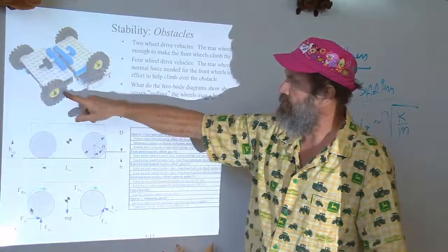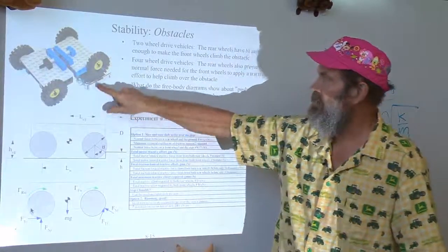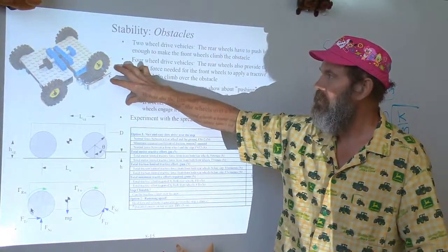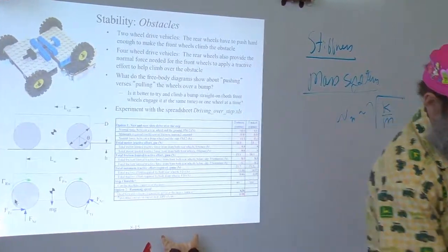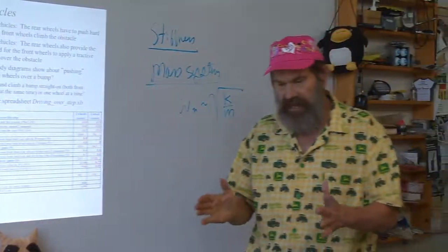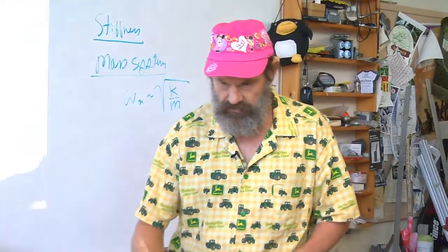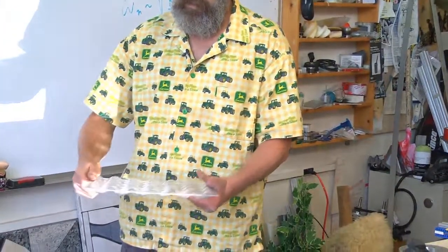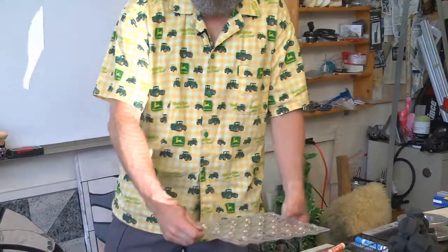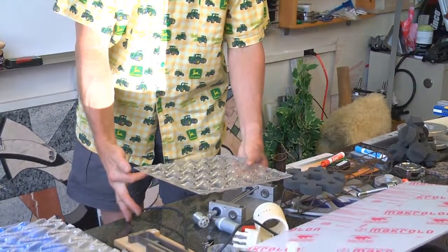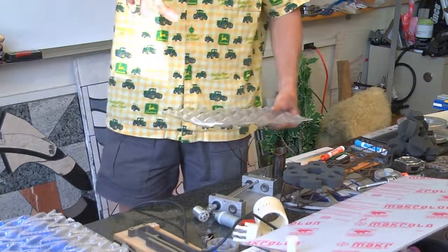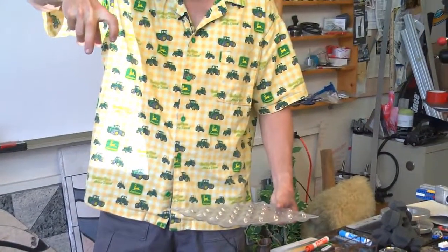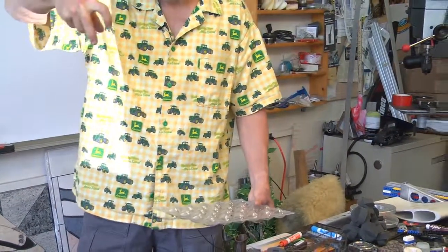For example, if this is a four-wheel vehicle and one tire has to go over a big rock, if the chassis was just a plate with four wheels on the corner, I would be coming along as I'm driving along into a condition where one wheel goes high and the machine, it would now be like a four-legged stool with one short, and the structure would rock and it would be unstable.